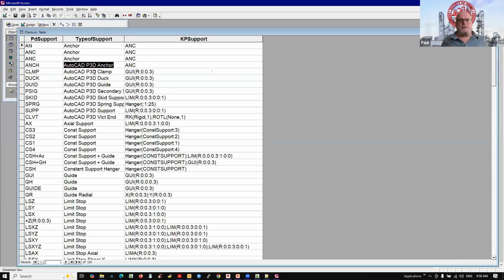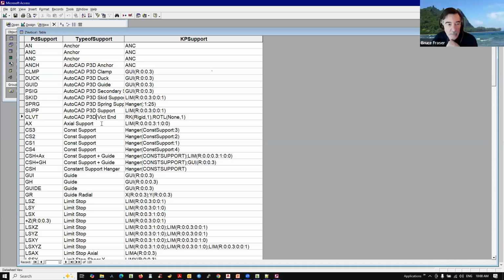Earlier you were mentioning that you don't have to place a support. You can place a potential support location if you just key in a node, right? Yeah, you put in the node, and then in theory that can be decided later. You just give a well point and it takes a node there. But what we are saying is we are already converting many of the things from here, in this case AutoCAD Plan 3D, into the corresponding mathematical support inside checkSTRESS.